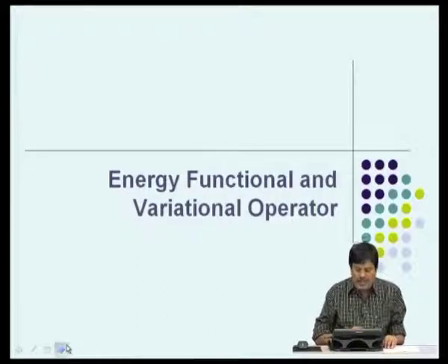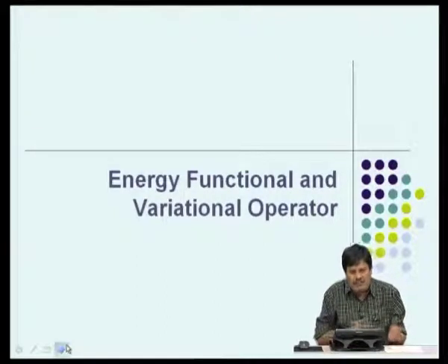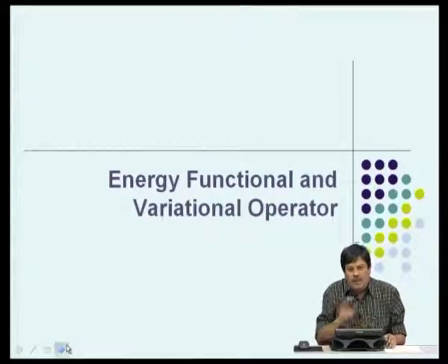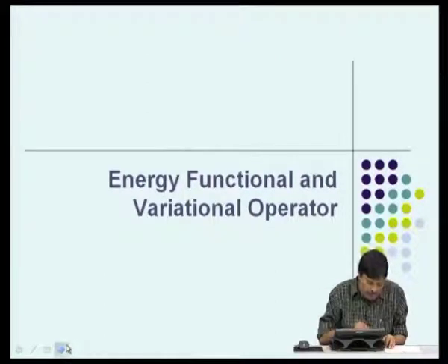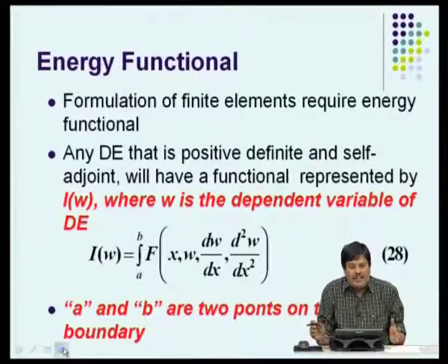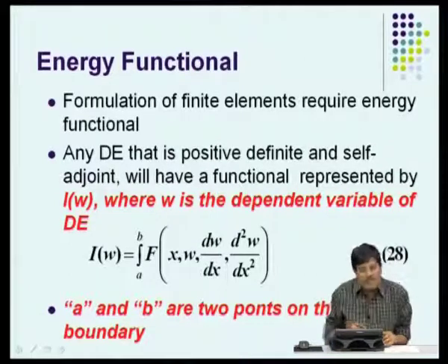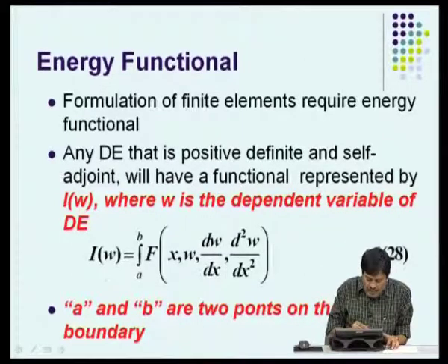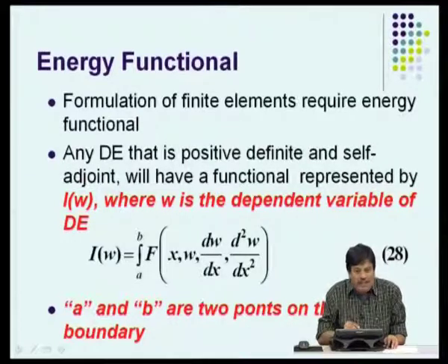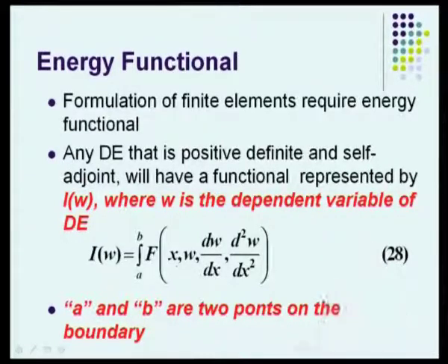Now, we will come to the definition of some of the energy functionals. We talked about it a little bit in the last lecture. We will go into a little more detail in this lecture and see what it means. So, what is an energy functional? The formulation of finite elements requires an energy functional. The energy functional has a broad definition. If you take the calculus of variation, it depends upon the spatial or independent variable x, the dependent variable w, its gradient with respect to x, the second order gradient and so on, where A and B are the 2 points on the domain.